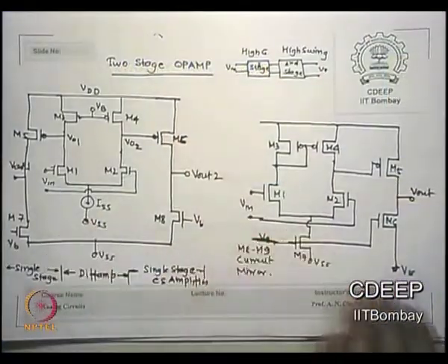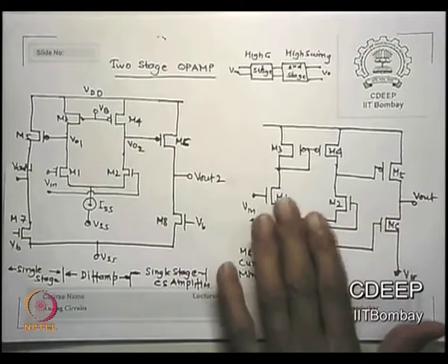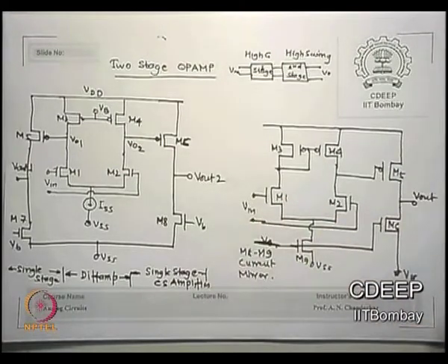Okay. This is the second part of this circuit, called single ended output, and what kind of loads are we using here? Mirror loads, okay, mirror loads. ISS is the bias current, gm is the square root of 2 beta dash W by L into ISS, and ro is 1 upon lambda ISS. So one can evaluate gm and ro. Remember, ISS increase and decrease will have opposite effects on gm and ro. So you may get reasonable gain. If you still want higher, double the sizes, increase W by L, okay. That is the way gains are adjusted, okay.